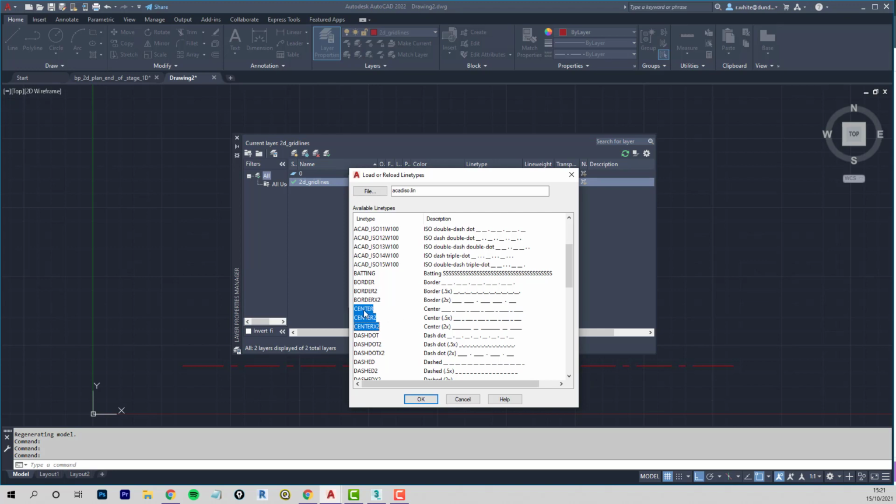Okay, what you don't do in a drawing is mix these end bits up. So if I wanted to add the dash dot line type to my drawing just now, I would use this version. Okay, the one that doesn't have anything on the end of it. Don't mix one that doesn't have anything with one that does. It gets really difficult to control your line types. So we would want to keep just using the ones that don't have anything added to them. Then we get a consistent control of the line types.